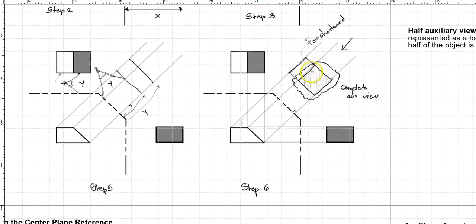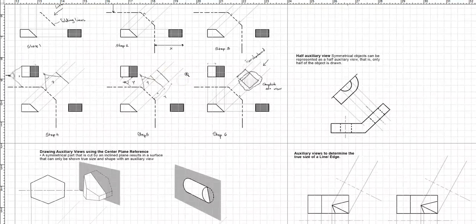So if I want to get the measurement for the top part, I have to get it from here. Okay, I cannot get it from here. Why? Because when I'm looking at the top part at an angle, I'm going to see that surface as foreshortened. So I hope you understood these 6 steps, but we are going to do a lot more exercises.